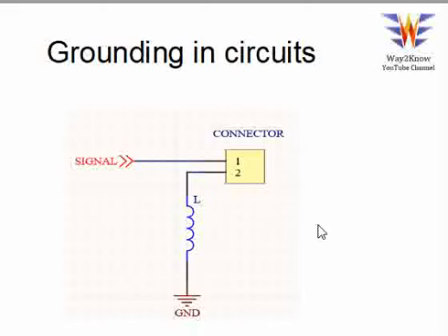Let us assume you have a huge circuit around this area in the PCB, and some noise on the PCB. That means there's some ground noise, which is causing an issue. In that scenario, the ground noise would pass by through this connector, and through the external connector there is every chance that it might leak.